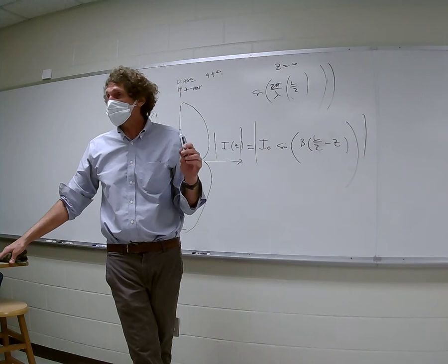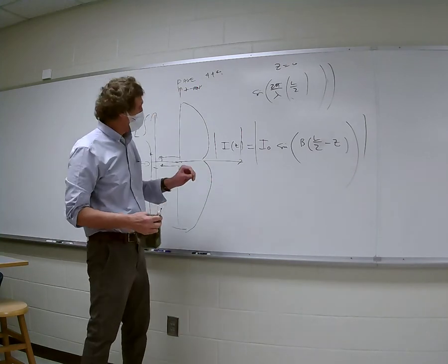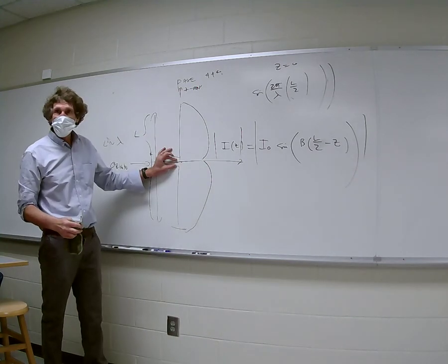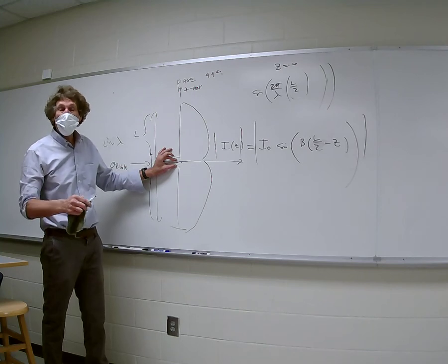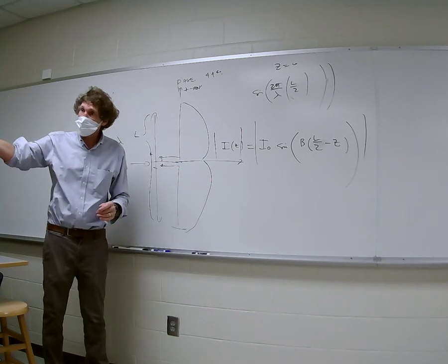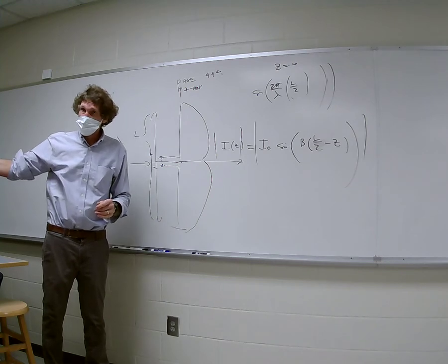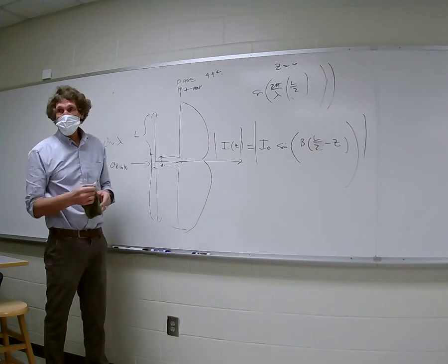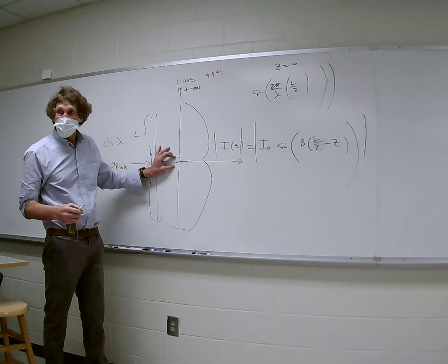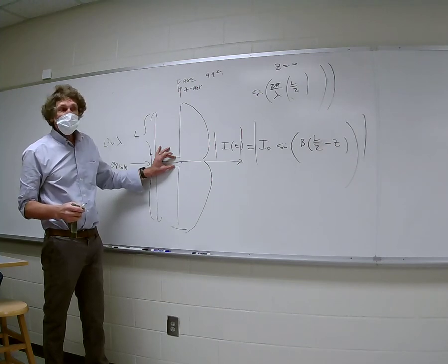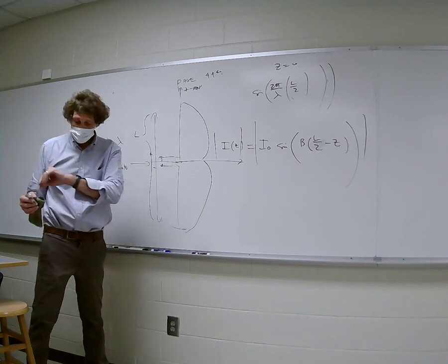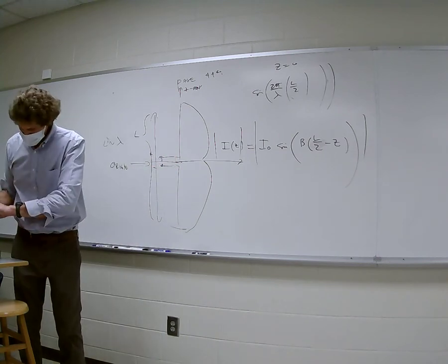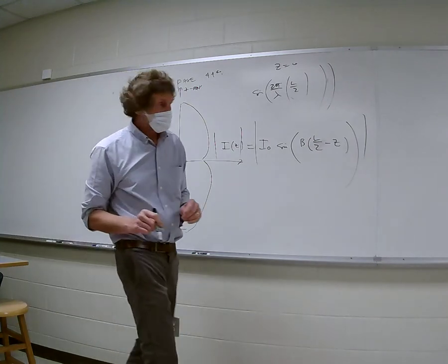So you have to understand that what happens to the feed point impedance of longer antennas is they go from something that we're going to calculate in a second that's a relative min, all the way up to infinity and back down to a relative min. Follow me? If you just take an arbitrarily long antenna and feed it, you can't bet you're going to find much current in there because the impedance is so high. Are you with me on this, everyone? There's a lot I can talk about. I have just enough time to do these slides.